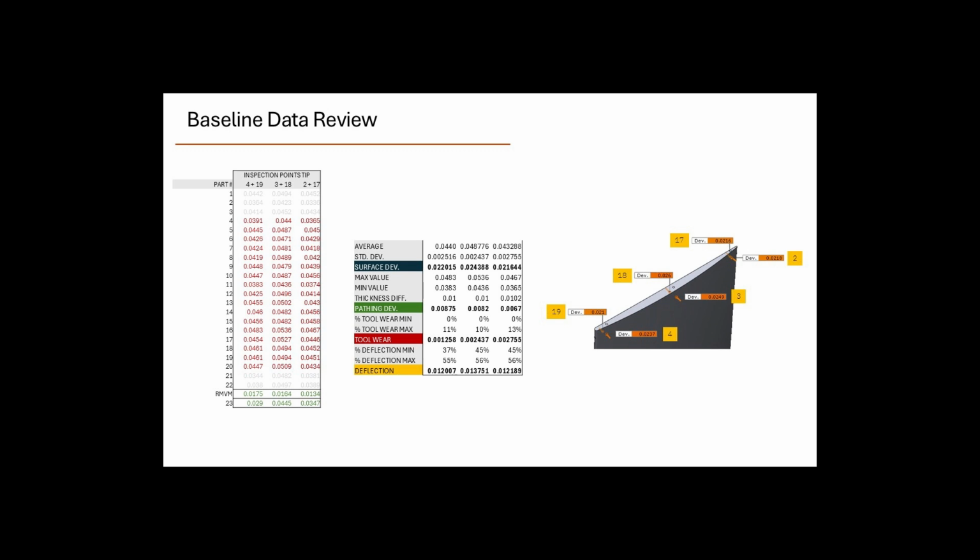The distortion as it shows up in the inspection results is going to be a positive deviation on either side of the blade. It's not going to help us. The distortion is happening in real time, and because the blade is rotating, it's distorting always in the negative Z direction. Therefore it causes a positive deviation on both surfaces. So we're running the analysis this way to basically eliminate having to look at distortion altogether.